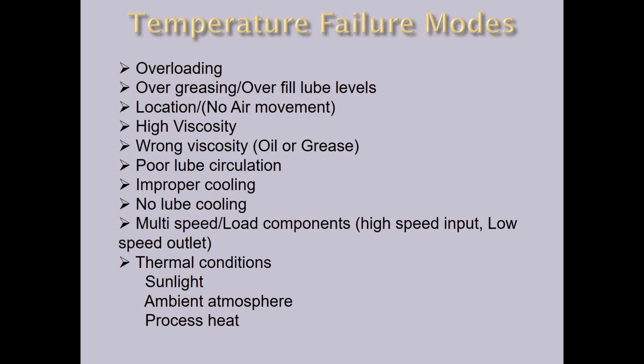Sometimes the ambient atmosphere that we've got our equipment installed in. Sometimes we have things with process heat. I've got one of my customers that processes lime. They have some gearboxes under some big rotary kilns. Well, the temperature under there is around 200 degrees, which creates problems with temperature on the gearbox. So they have to do other things with viscosity and other methods to keep that oil and extend the equipment life.